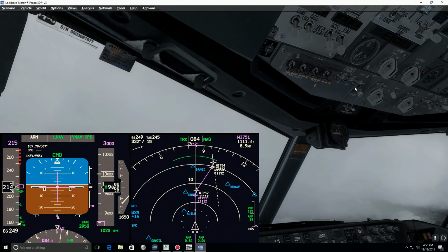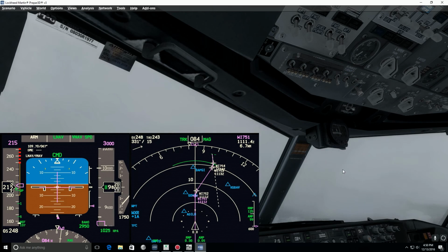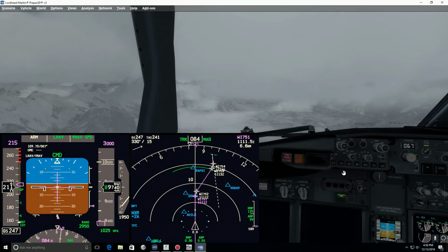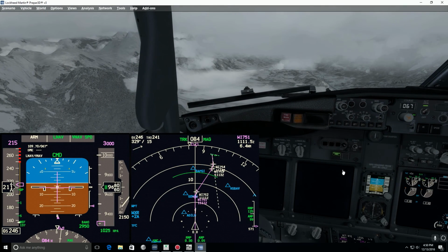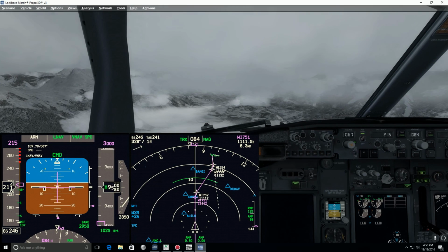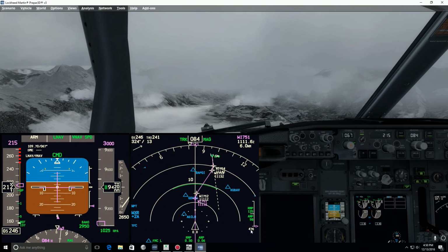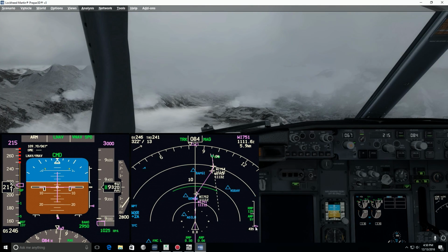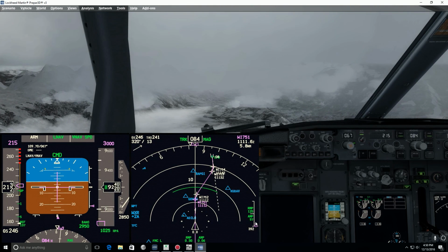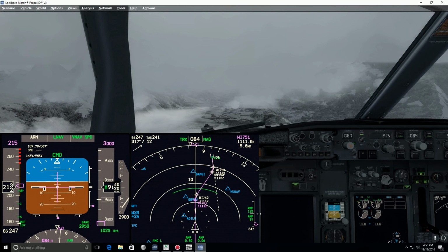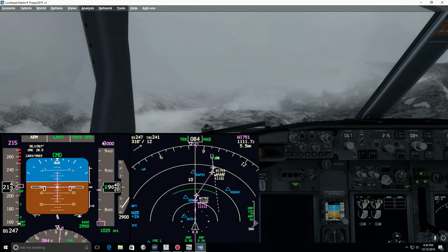Retractable lights on, and the 2 runway turn-off are on. Now with the gear, for sure, it has a lot of drag. We are going down nicely. We are going back into here. The path is coming back. And now the mode should revert to VNAV path.